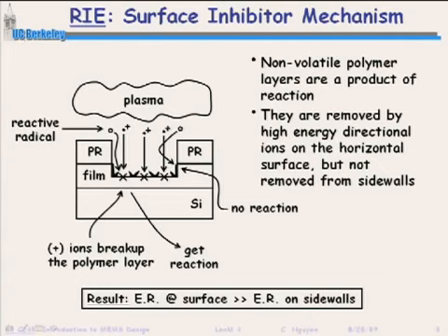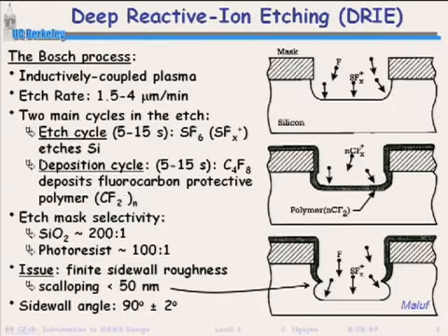And so in technologies like CMOS and transistor technologies, a lot of the art of design in those technologies is to try to design them such that the layers you're etching are very thin. Right? And why do we want to do that? Because thinner layers means less topography, which means that your lithography can be much more accurate. Okay? So in CMOS, you want to keep everything as flat as possible. You'd like to do that in MEMS too, but often you can't because, you know, just the nature of it. There's a lot of 3D things that have very high aspect ratios.